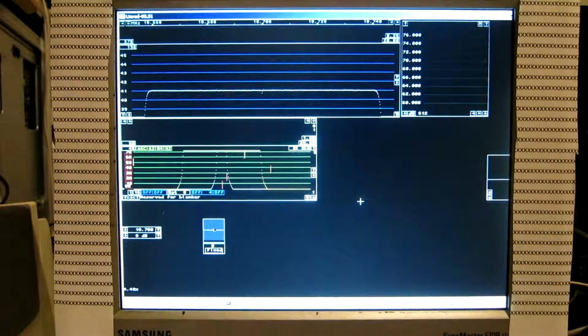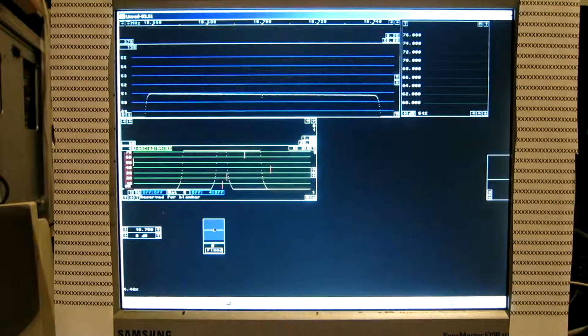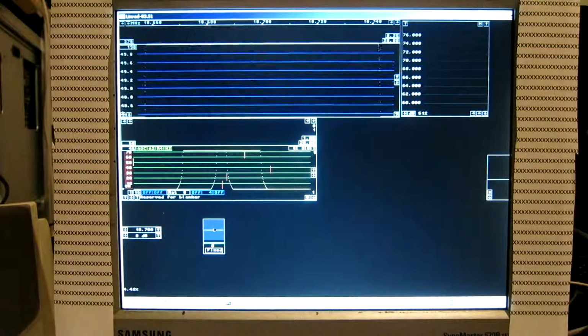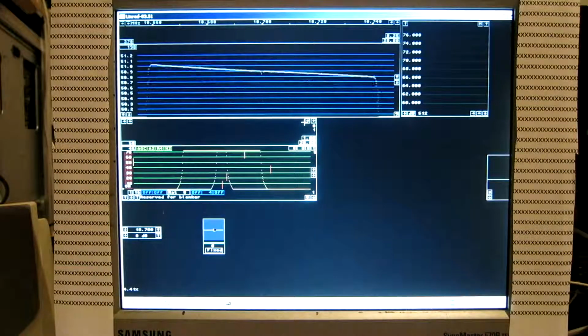Now I increase the signal level by 10 dB. This is to verify that the shape didn't change. And you can see actually it did. It now slopes just a little bit from here to here. I can expand the dB scale a little bit extra. We have a slope of about 0.2 dB, and that is with 5 volts amplitude on the incoming pulses.